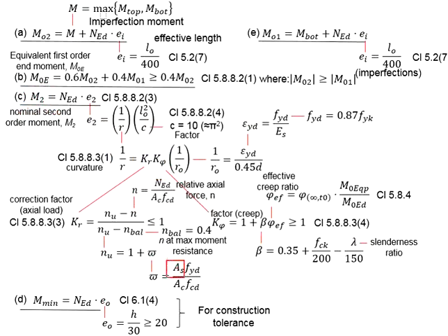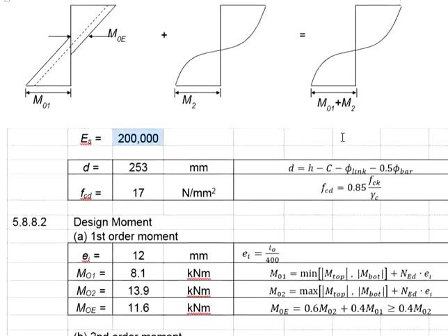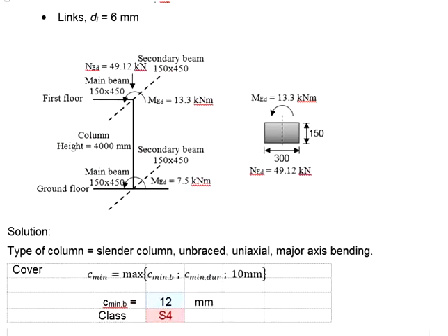Since we do not know the amount of reinforcement bar, what is for sure is that this definitely shouldn't be equal to 0. That means ultimately it may end up being a certain value, which at the moment we do not know. Therefore, our calculation steps shall normally start with assuming the Kr equals 1.0. This process is similar to the questions that we did previously regarding the slender column of the umbrella structure with the moment acting in the major axis.